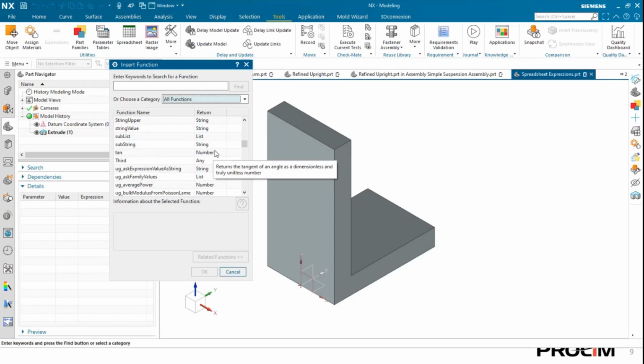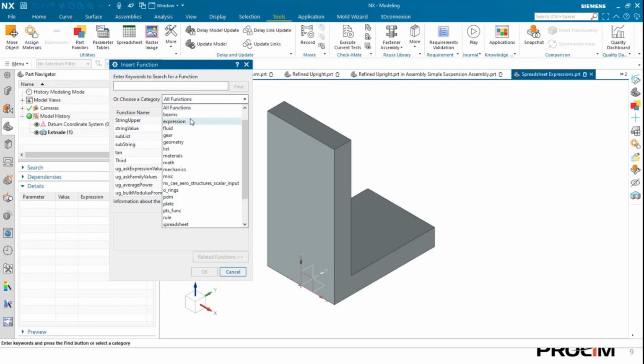Well, if that really annoys you, you can actually go into your expressions table and change that Boolean function to a function like this, where it says, hey, if my value of this is less than 0, change to subtract, and if it's more than 0, change it to unite. So that's a very simple example of where you could use logic in your expressions. And that's some very advanced stuff if you're doing that.